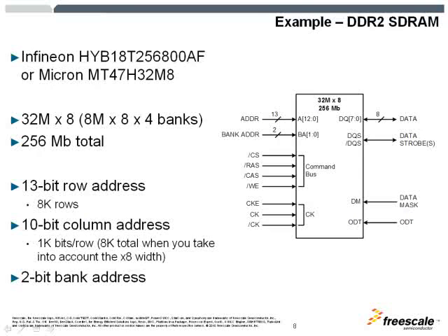One is the data bus, which consists of the DQ, or the byte, and DQS, or strobe, and data mask, or DM. All these signals operate together as a bus, independent of the other signals. The other signals, which are address, command, and control signals and clocks, operate as the other bus, which is called the address and command bus.